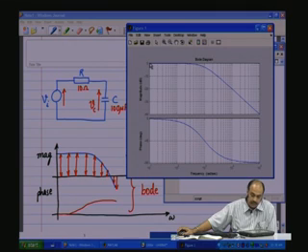During the frequencies which are DC and close to the DC, this capacitance is something like an open circuit. Whatever you apply at the input comes to the output. And during the portion when the frequency starts increasing still much higher, the capacitance starts giving lower and lower impedance. Ultimately, at very high frequencies, this will act as a short, and the output will go towards 0, and therefore, the attenuation keeps going.